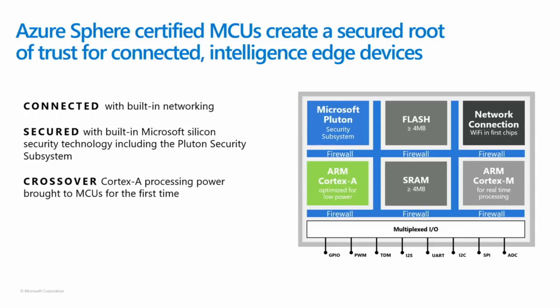When you look at a typical MCU, if you're in this space, you're talking about something like a Cortex-M. Cortex-M has physical addressing. It lacks a lot of the properties we're looking for. Across our MCU, we have both a Cortex-M and a Cortex-A. A Cortex-A gives us address translation, lets us run a higher level operating system based on something like the Linux kernel, has SRAM and flash, and is protected by a bunch of what we're calling silicon countermeasures that help guard against software that ends up being exploited.